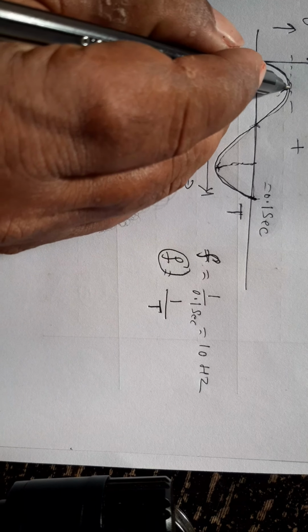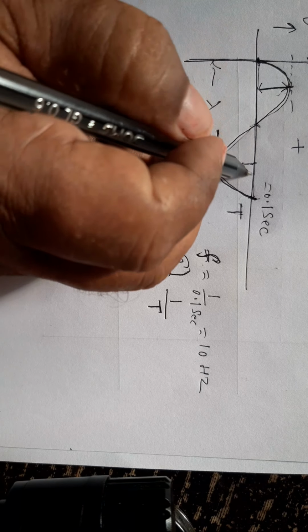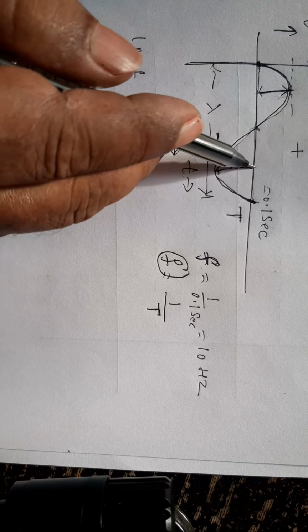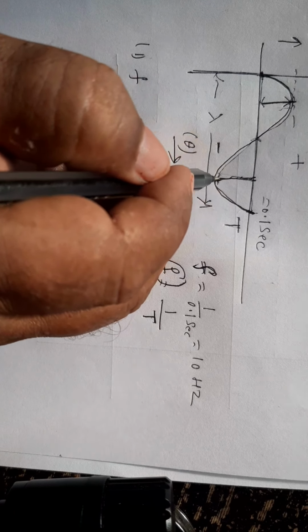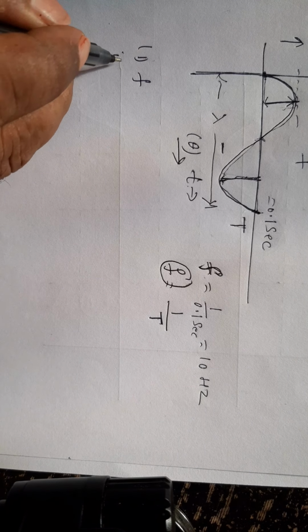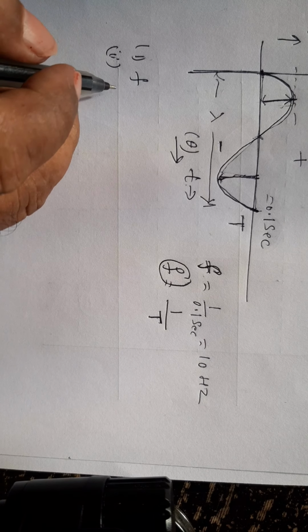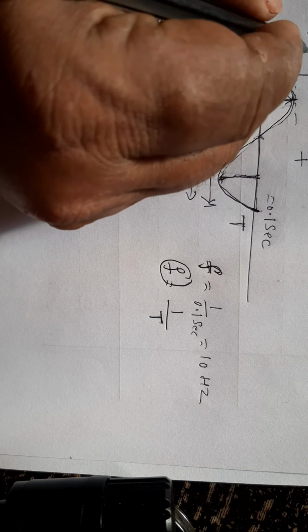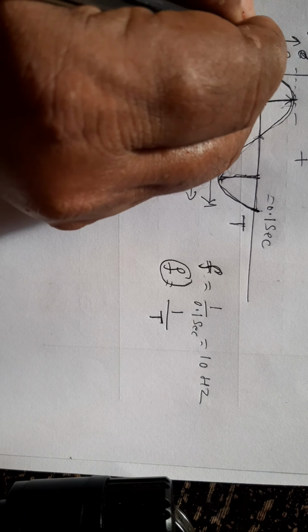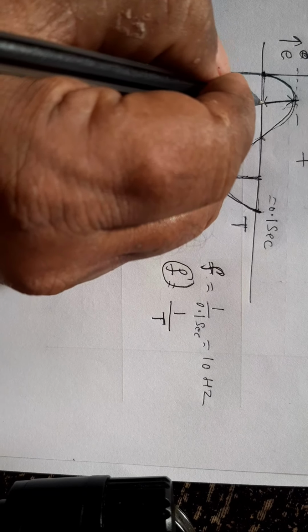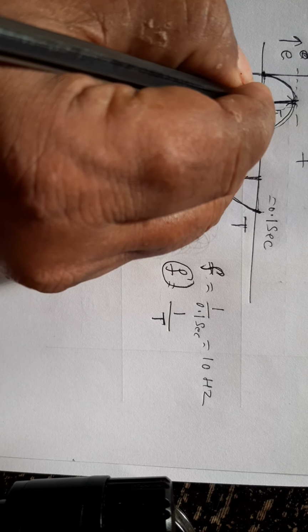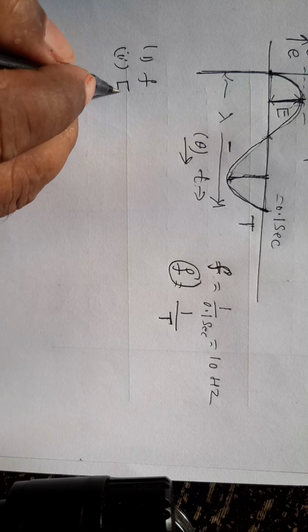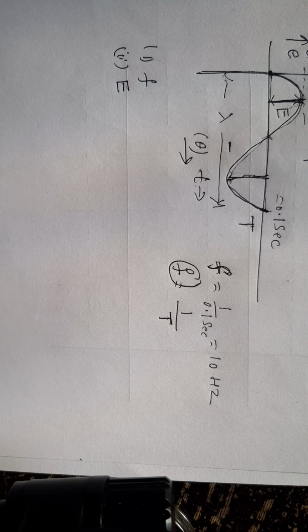Thus, a wave continuously changes in its voltage. The maximum voltage of a given wave, either on the positive side or on the negative side, is called amplitude. Therefore, the second very important characteristic is called amplitude. If I represent the voltage as small e, I will represent the maximum amplitude as capital E. So, E is the amplitude, that is the maximum value of a given wave, either on the positive cycle or the negative cycle.